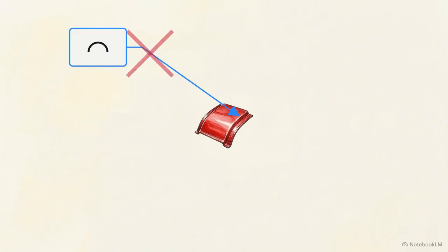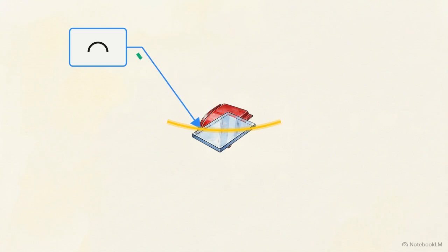A common error in industry is incorrectly pointing a line profile symbol at an entire three-dimensional surface, like this curved car roof. Profile of a line evaluates individual cross-sections independently, not the whole surface at once. The inspection requirements are vastly different. Line profile only requires verifying specific two-dimensional slices. Surface profile requires a sweeping laser grid to map and control the entire three-dimensional boundary simultaneously.